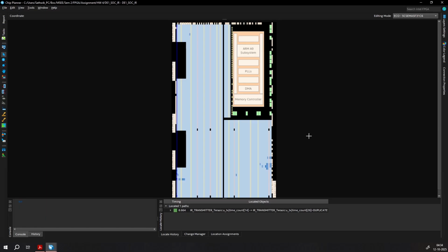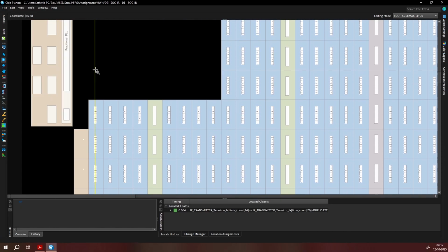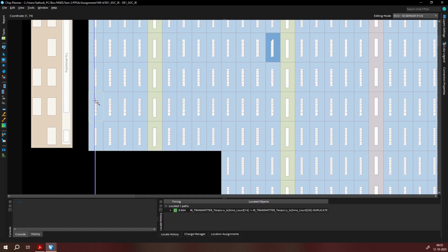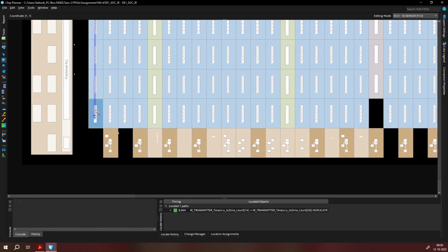Comparing this resource placement to the previous, where everything was clustered to the right side of the chip, but later we moved the resources to the left corner, bottom left corner and top left corner. All of them have been clustered more towards the left to avoid the delay as much as possible. So here is the base of the resources, which then goes to the top module and then comes down all the way to the bottom of the chip and then again routes back to the middle of the chip.